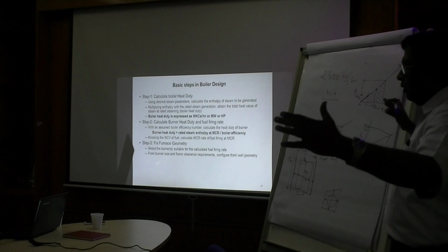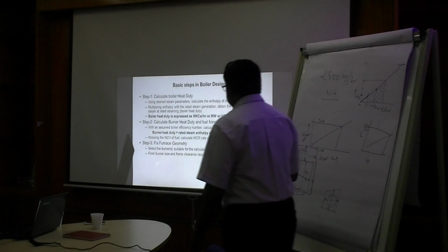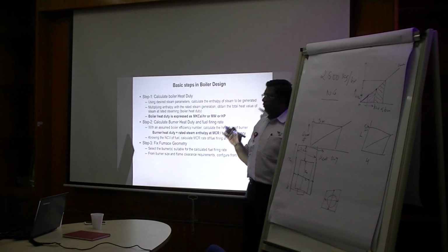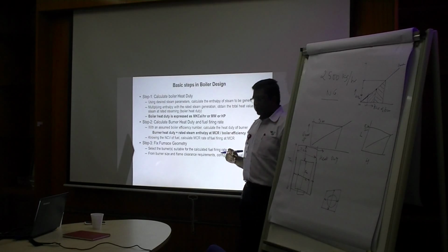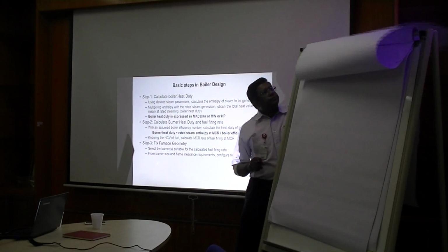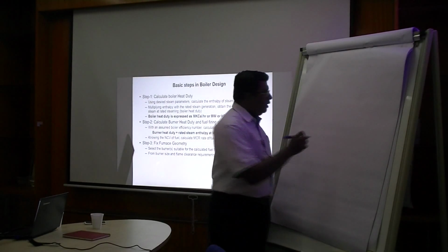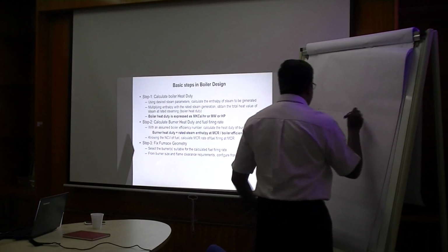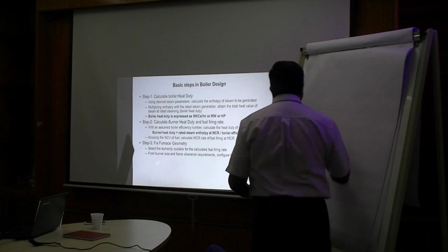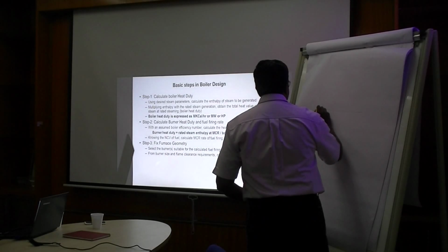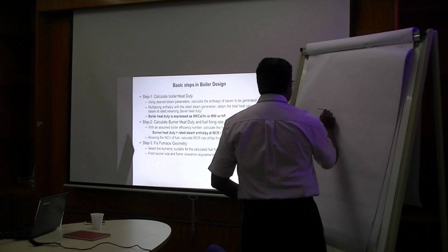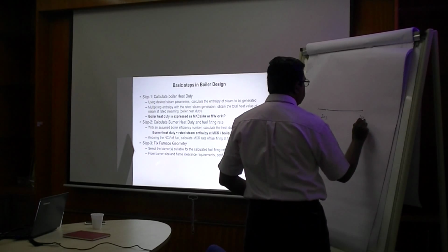One burner can turn down from X to 1/4 X, 25% normally. But if you want a whole boiler, let's say now, while ordering the boiler, you order for a load range of 20% to 100%. Take this case. Our requirement is that boiler load should be able to cater to 20% to 100%.